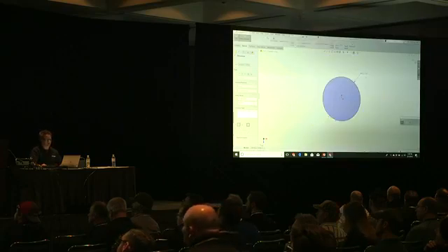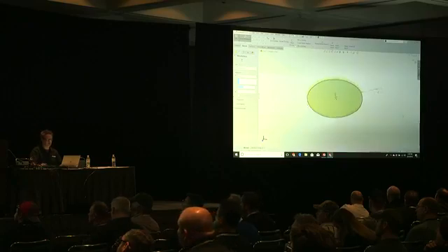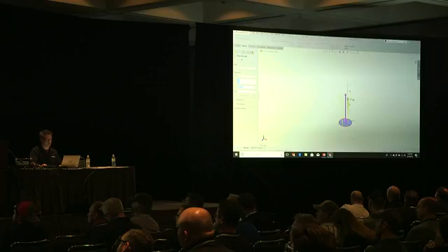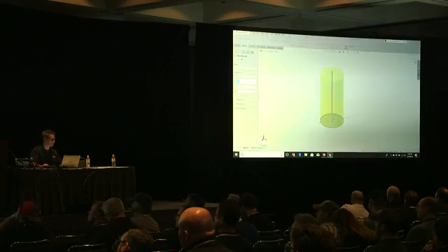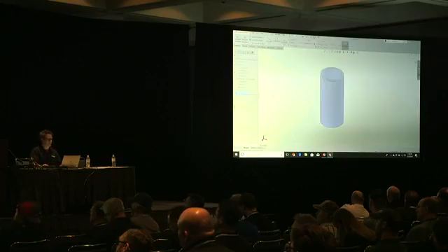And then I put my shortcut key on my gesture so that I can just grab it. Now, everybody knows the mouse roll, zoom. If you hold down Control and your mouse, you pan. So I do a lot of that when I'm plugging through, like this. I'm going to do a thin feature. I'm going to flip it. Now I have a tube. Front plane sketch.